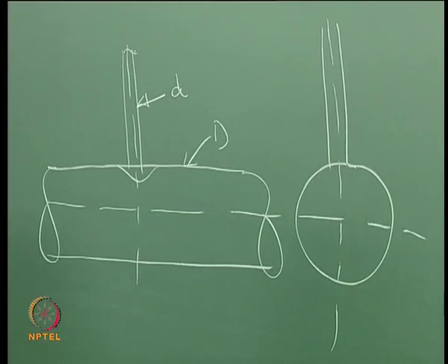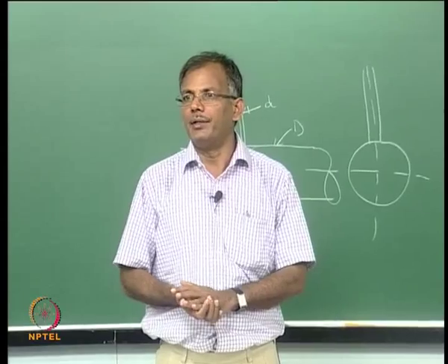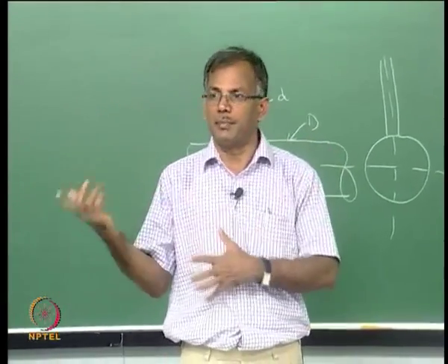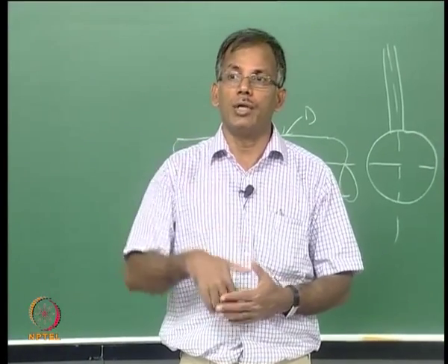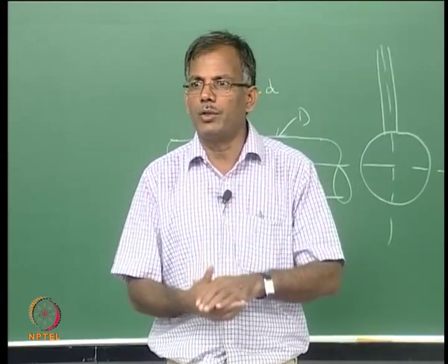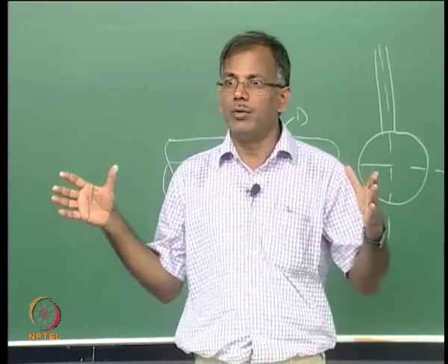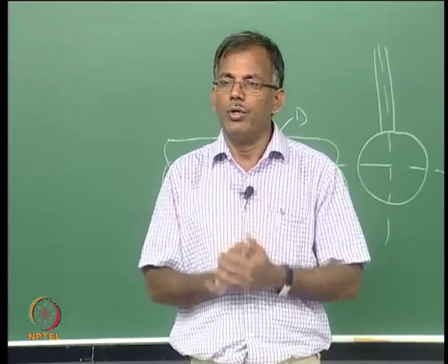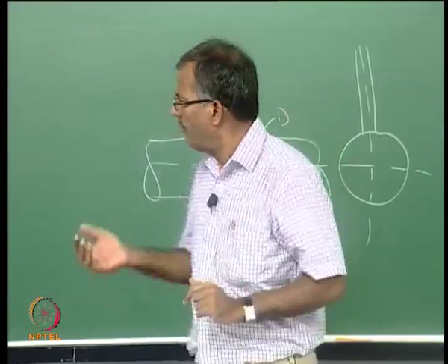In this kind of scenario, you will get this in many places, because you normally do not want to oversize the brace unless it is required. But the chord, this could be a jacket leg, the leg is designed for some other purpose, by making it have the piles going through the legs. So you might have a very big leg, but the brace could be quite small. A typical example will be the brace may be 500 mm, but the jacket leg could be 2 meters. So you just come to 0.25, 1 in 4. That is the kind of situation where you can see the behavior could be almost local.